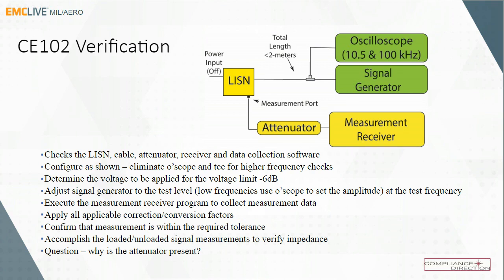After that, you may or may not need it because the LISN capacitor tends to attenuate the signal. Anyway, this checks the LISN, the cable, the attenuator, the receiver, and the data collection software. We configure it like we show there.